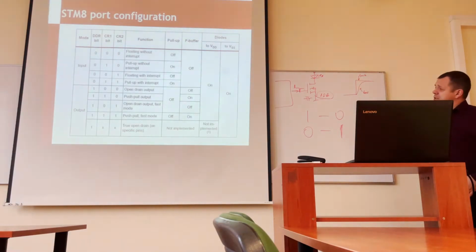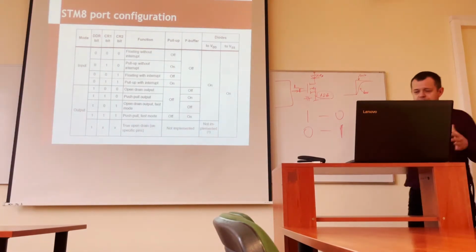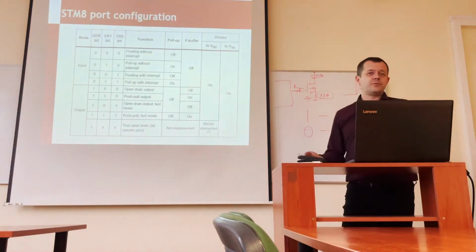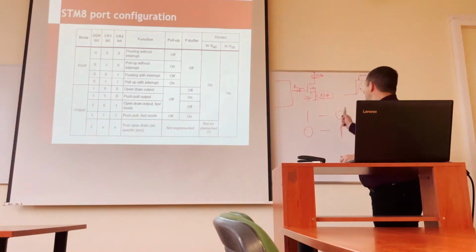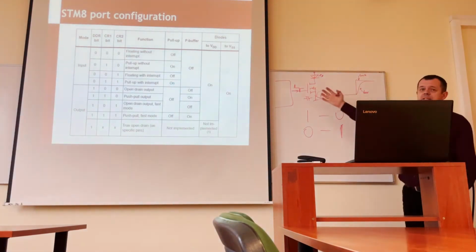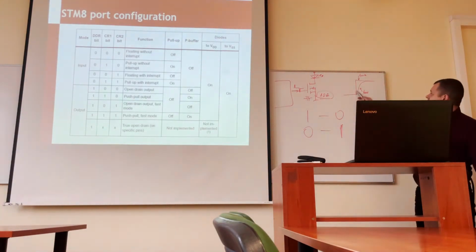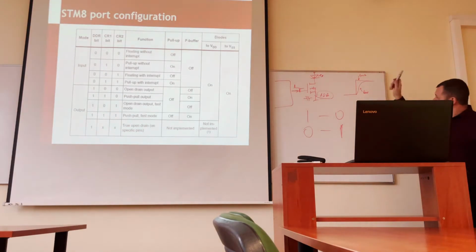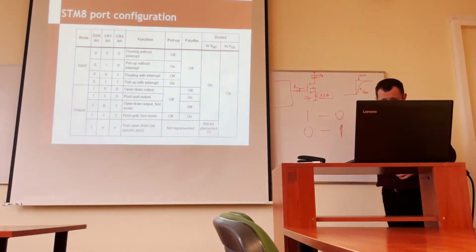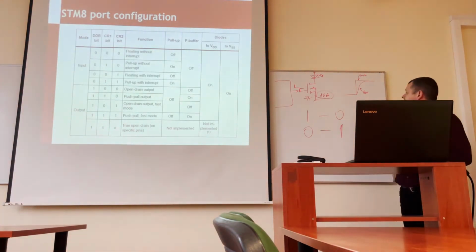The problem, unfortunately, with fast mode is that if we make a Fourier transform of this fast switching, we end up with a high bandwidth of noise coming from it, which means these fast noises propagate very nicely into other tracks, paths or pins, because this generates an impulse of wide bandwidth.